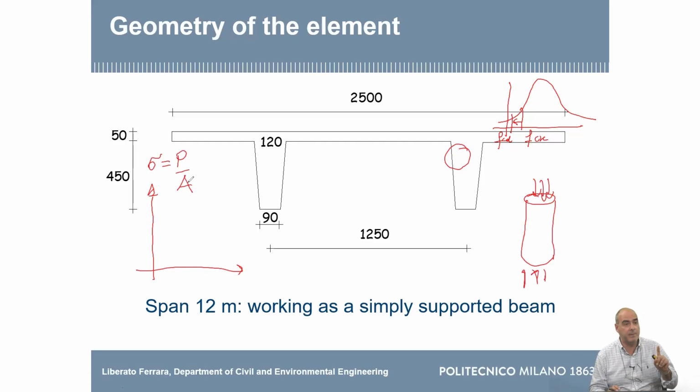Remember, you never measure a stress. Stress is a quantity that we cannot measure. We measure a deformation, and in load cells, through that deformation, we convert into a load. The stress we always calculate based on an assumption. And the assumption under compressive load is that the stresses are uniformly distributed over the cross-section. So the stress is load divided by area.